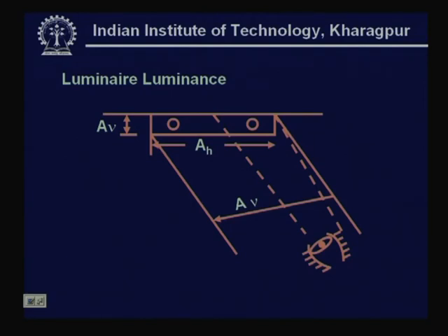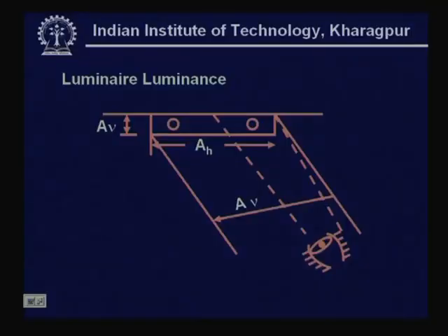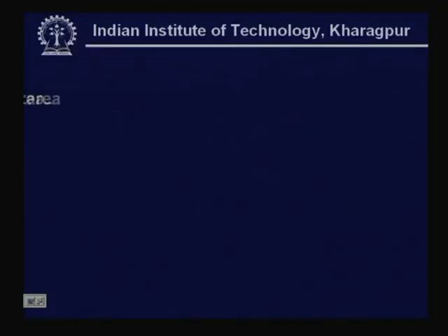How does one take care of luminance? Because we said the three steps that are involved in assessing are: 1, use of the tables which have the numerical values; 2, the graphical diagrams in terms of Isolux diagrams; thirdly, the luminance for the luminaire in candela per meter square.